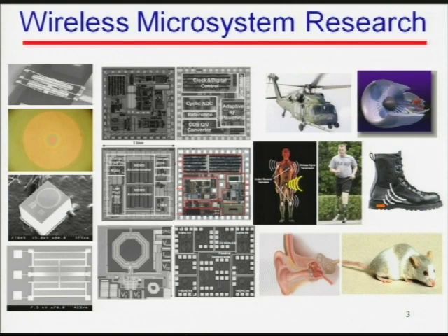This is an accelerometer that puts into, where did I put this? Or this puts into our middle ear, on the ossicular chain behind the tympanic membrane, so that as you're talking to a deaf person, the eardrum will vibrate and couple the mechanical vibration to the ossicular chain, or what we call the hearing bones. So the sensor will vibrate. This accelerometer will pick up the vibration signal and convert it to an electrical signal, which can be used as an implantable microphone. So all of these devices require some sophisticated electronics design.